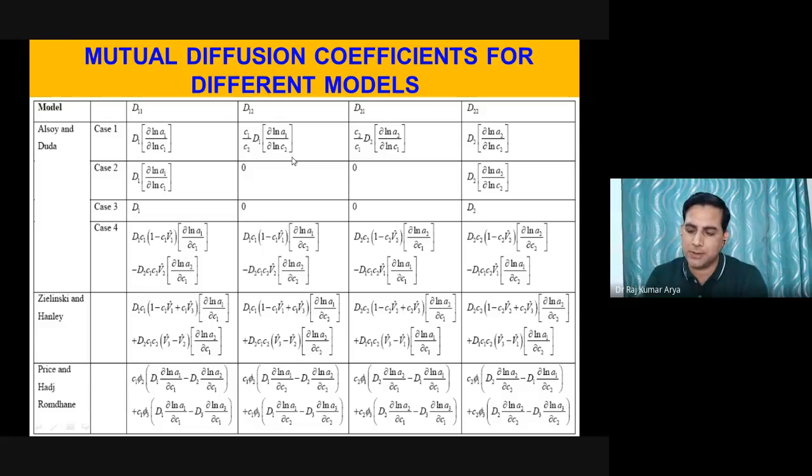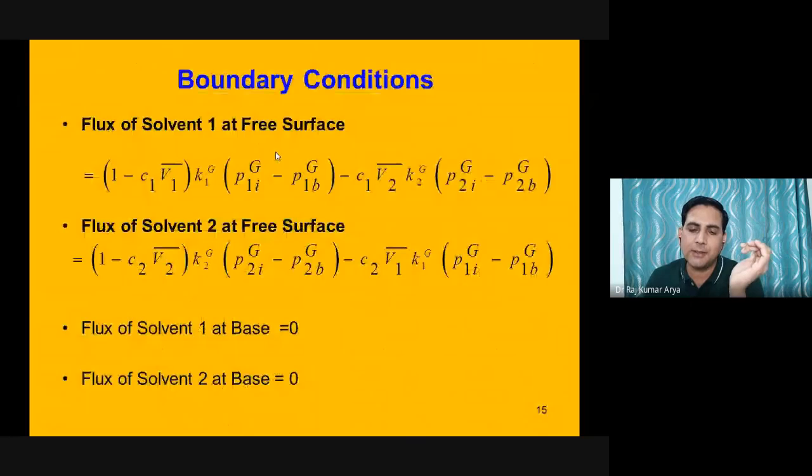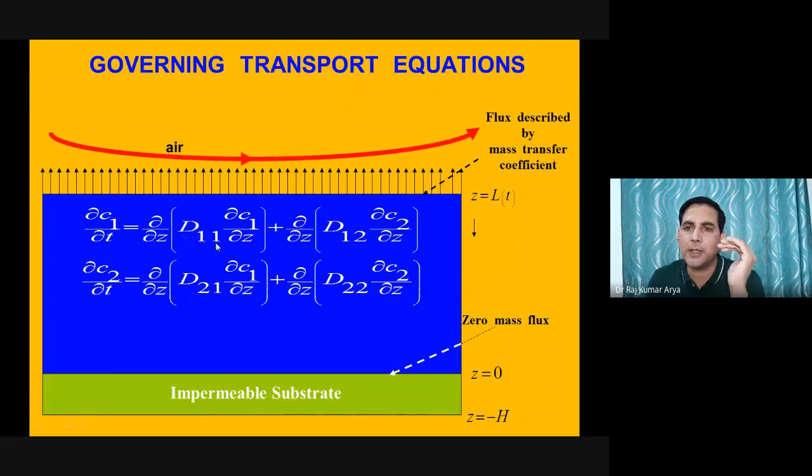So we have those, considering that we want to do only the modeling simulation part. We need all the model equations that need to be solved, because we need to know what D11 is and how I would calculate it. So I need a model equation for this parameter. The diffusion coefficient cannot be treated as constant because initially you will have a very high amount of solvent, and then later on you will have the solvent at 1 to 2%. So the diffusion coefficient is a function of the solvent mass fraction also. So you need the model equations for that.